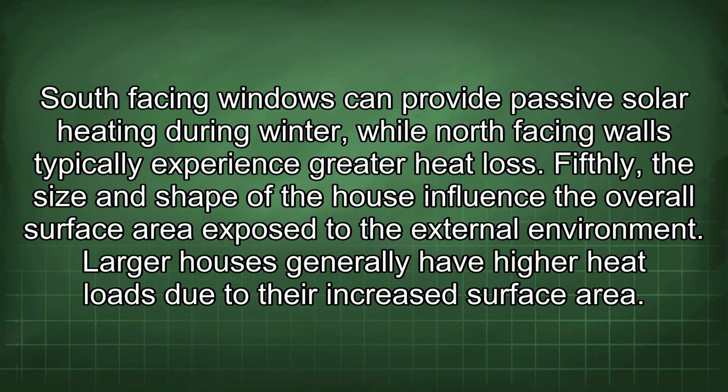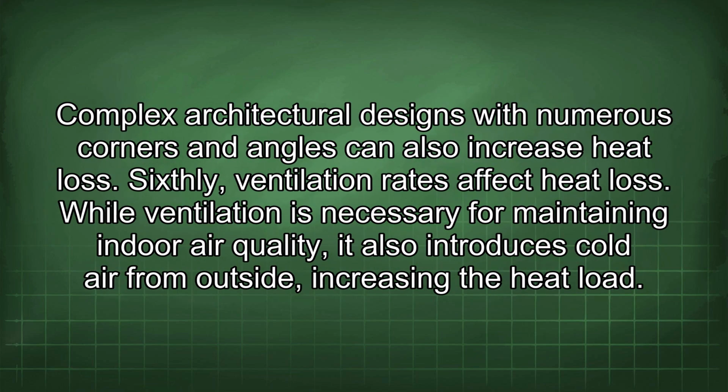Fifthly, the size and shape of the house influence the overall surface area exposed to the external environment. Larger houses generally have higher heat loads due to their increased surface area. Complex architectural designs with numerous corners and angles can also increase heat loss.